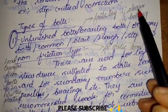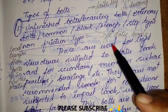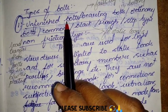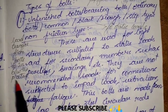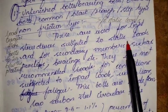This fails by shear and bearing. So for static loads, generally we are using these unfinished bolts. Here the load transfers from the bolts to the plates in between. Generally these are used for light structures subject to static loads.